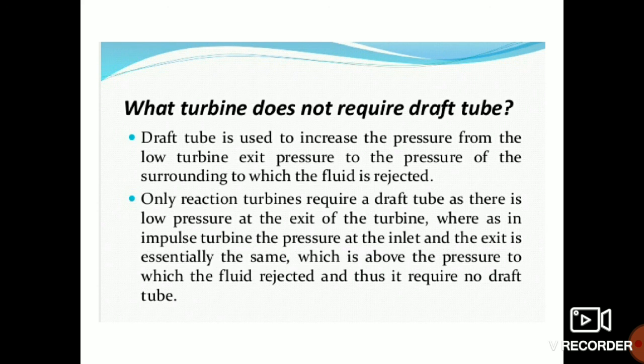Only a reaction turbine requires a draft tube, as there is low pressure at the exit of the turbine, whereas in a simple impulse turbine, the inlet and the exit pressure is essentially the same, which is above the pressure to which the fluid is rejected, and thus it requires no draft tube.